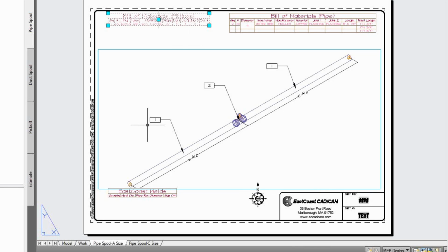Because these are not in the same space, we have to go through some tricks in order to get them to schedule. To do that, we set it to scan for XREFs, and then our software will automatically come in, and the XREF that this is looking for is actually the same drawing. That allows it to have your schedule in paper space and go into model space and schedule those items.